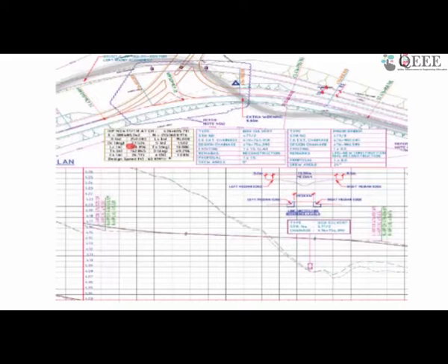It is much more prominent in the railways, because the branch out can happen on the curve, whereas in highways we have better control and we don't want the branch out to happen on the curve but on the tangent sections, to avoid any negative super elevation. So with super elevation, you need your outer edge to be raised. If, because of certain constraints, you are not raising your outer edge but you are raising your inner edge, that is your negative super elevation.